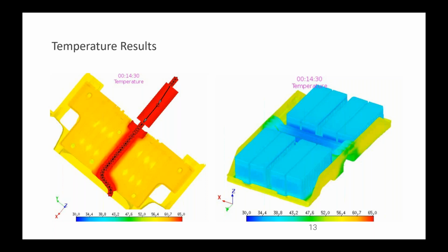So it's important to recognize heat sources both inside and outside the pack. While the vehicle is being driven in electrical mode, you need to dissipate all of the heat inside the pack, or enough to maintain the lifetime of the batteries. And then whenever the vehicle's driving in combustion engine mode, you have to shield that pack from external components getting too hot.